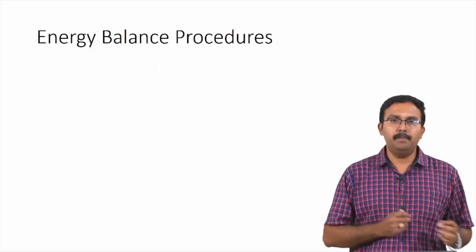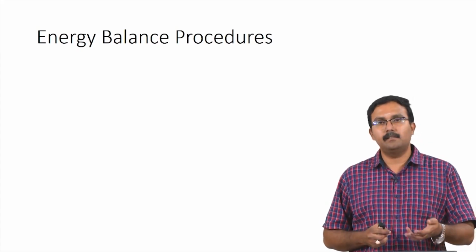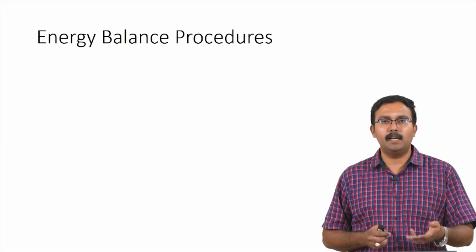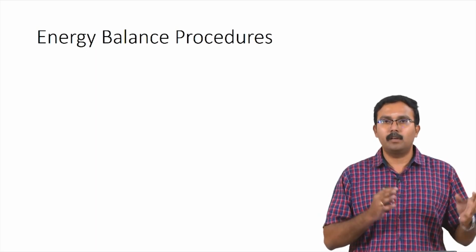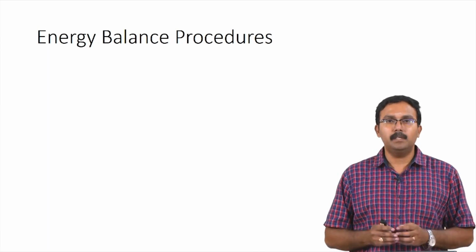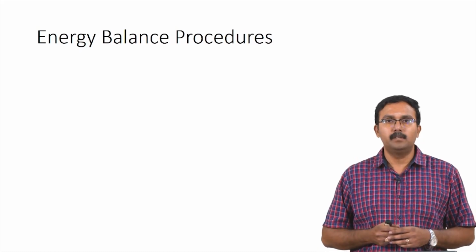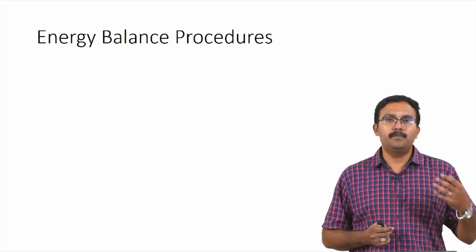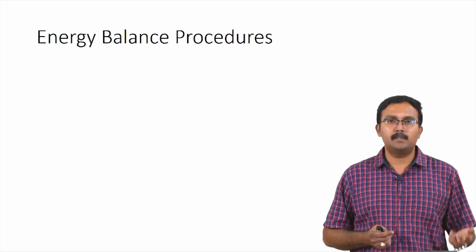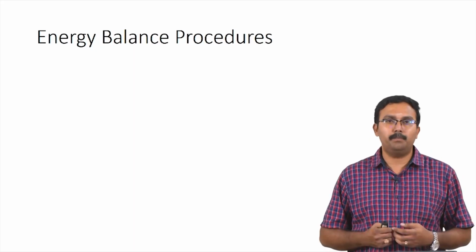you need to have completed material balances. In some cases, especially in exam settings and in assignments which I hand out, you might end up having material balances already solved for you. However, in real life scenarios, material balances might not be solved for you. So, if you are going to design a plant and you need to understand the energy requirements, you first need to complete all the material balances which are associated with it, so that you know how much energy would be required for each of the process.